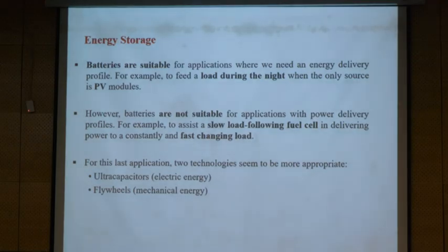Yes. What are the different reasons for fast and slow oscillation in the system? Different reasons. I mean, it depends on what kind of grid you have. If we get back to the power system and go to more renewables, the conventional synchronous generators in the power plant are connected in parallel together. In a parallel connection, the impedances are in parallel. So if you have 10 generators connected in parallel, Z is Z over 10.